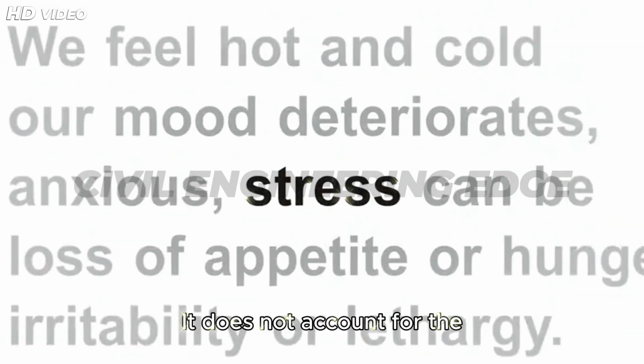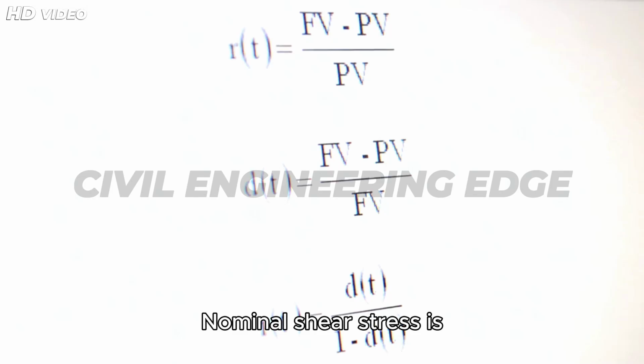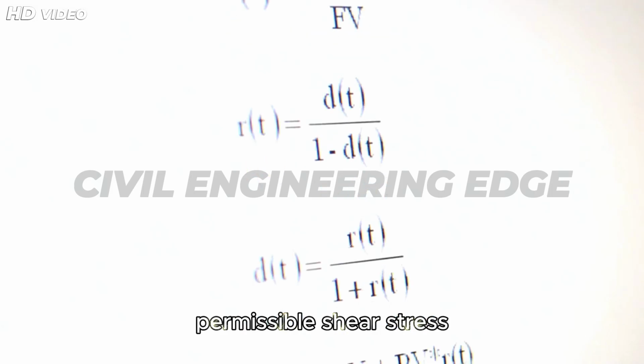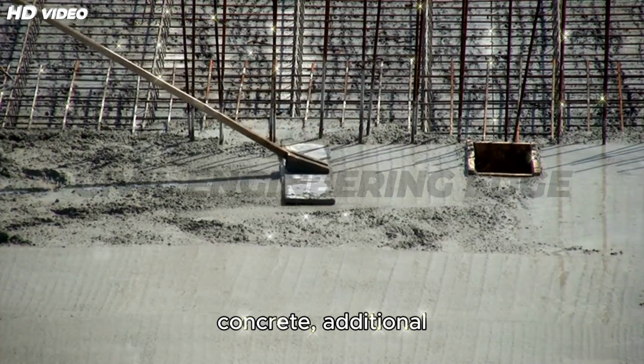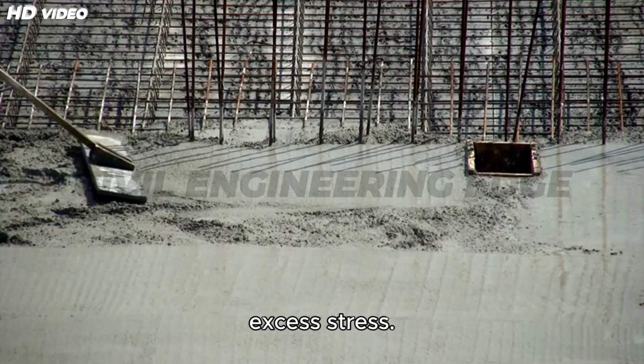It does not account for the shape of stress distribution or reinforcement presence. Nominal shear stress is primarily used to compare the beam's capacity against permissible shear stress values given in design codes. If tau exceeds the design shear strength of concrete, additional shear reinforcement is necessary to resist the excess stress.